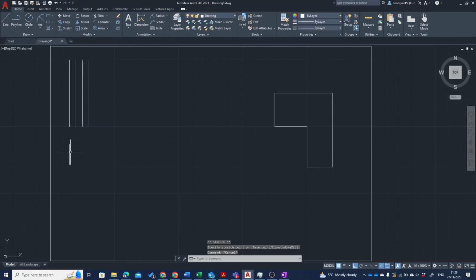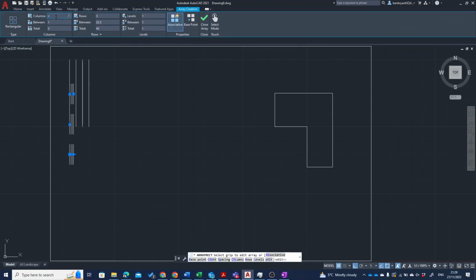So click on this one, rectangular array, and so I would like 4 columns, I like 1 row. So enter that into the system first. That'll give you the parts. The distance between on the rows, or distance between here. So I want 5 mil.